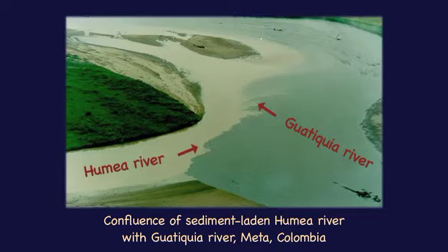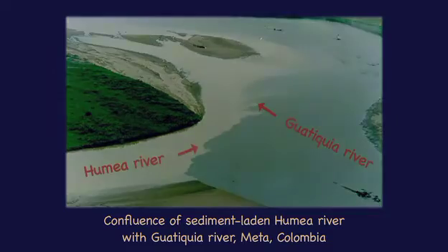All natural streams carry a certain amount of sediments. Normal sediment loads are in the range 200 to 300 parts per million. Sediment-laden rivers may carry more than 1,000 parts per million. The amount of dissolved solids carried by streams in the contiguous United States has been estimated at more than 50% of the amount of suspended solids.